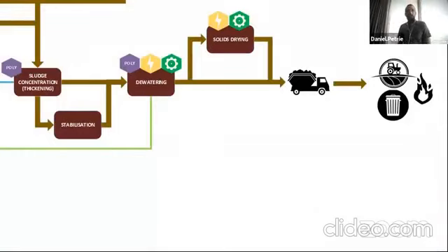Okay, so if it's very expensive to transport your sludge or to dewater it, dispose of it or incinerate it, then you might say, all right, the cost is tied still to the volume of material that I'm having to move around. If I could drive off more water from that sludge, then the volumes would come down significantly. So from a 30 to 40% solid cake coming off your dewatering process, maybe you can push that up to 60, 80% solids if it was dried. To get that, you have to apply heat.